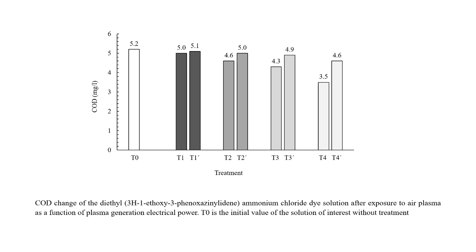The most effective organic matter removal is obtained with the treatments at atmospheric pressure. The highest percentages of COD reduction are attributed to the dye's exposure to non-thermal plasma generated in the presence of a greater number of air molecules. The multiple reactions that take place favor the removal of organic matter. Plasmas in the presence of air can generate ultraviolet light in situ and numerous reactive oxygen species.